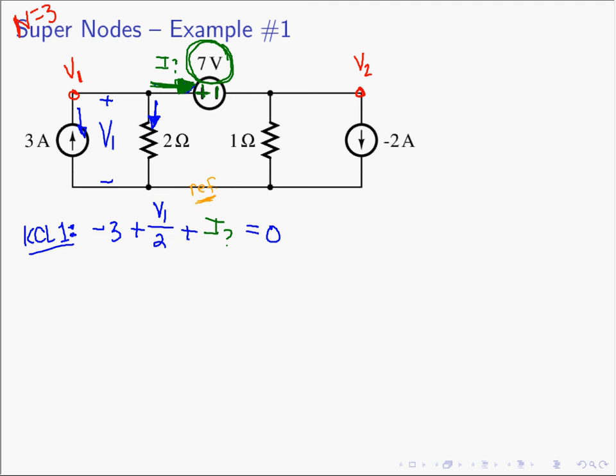Okay, so let's hop over and do KCL, equation 2, for node 2. What's the current going down in this direction? The currents line up, so it's going to be minus 2 amperes. What's the current flowing down this direction? Remember, it's plus to minus V2, so since we're doing the current leaving the node, the passive sign convention sets up naturally. So the current going down is V2 flowing through a 1 ohm resistor.